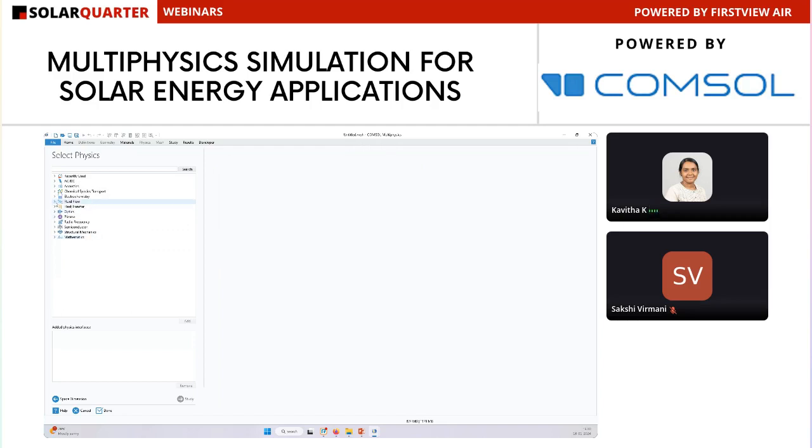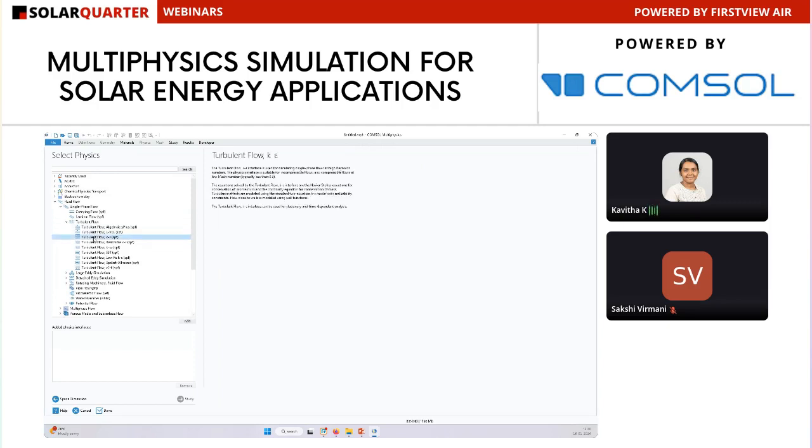So in our example, we are going to model the fluid flow for the air flow, or the wind flow, around the solar panel. So let's first choose fluid flow, and we are going to have single-phase flow and turbulent flow, and we are going to model the turbulent flow k-epsilon. We are going to use this physics interface. Let me choose add.